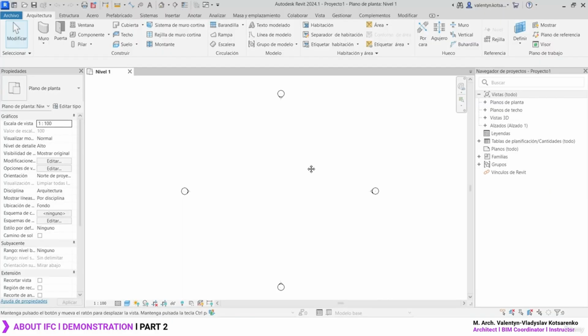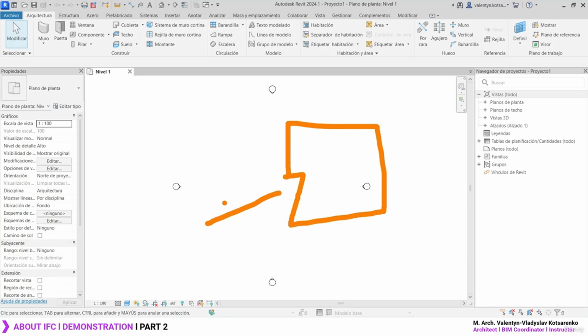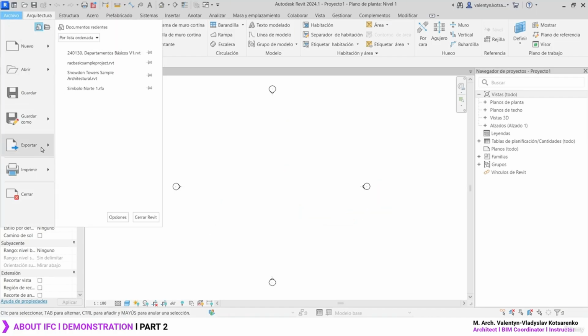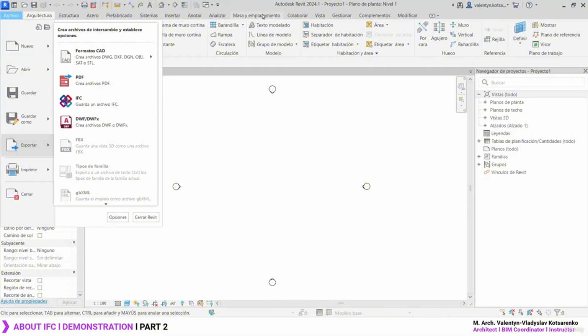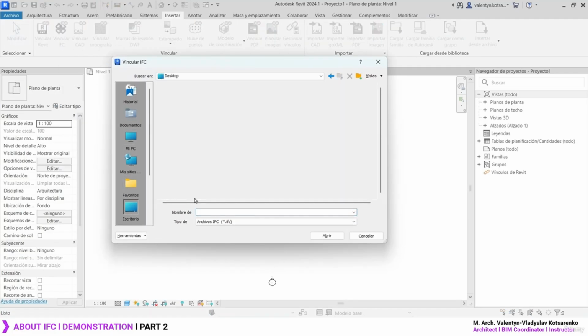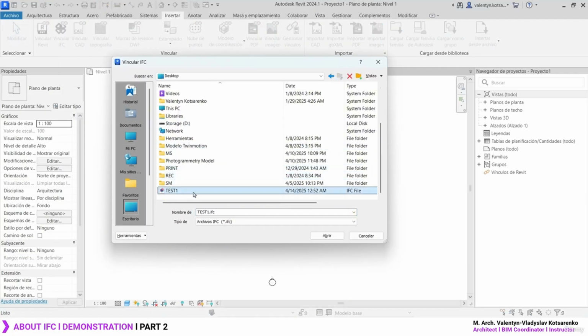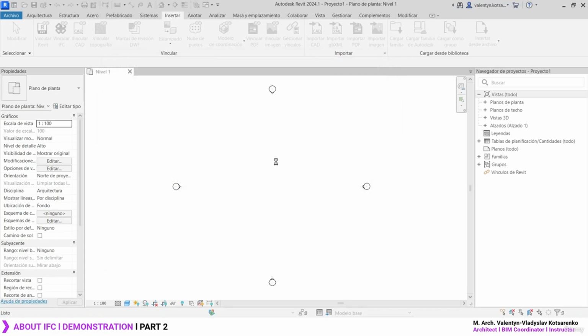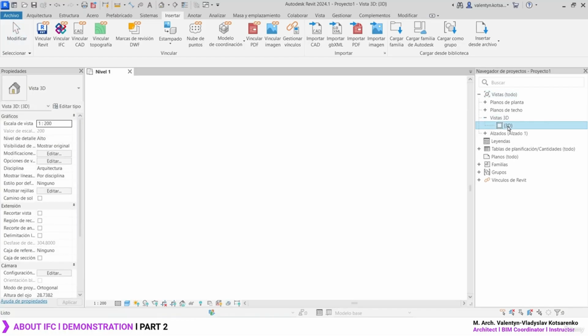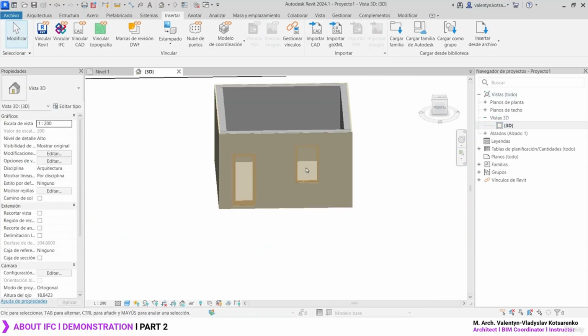Let's say I have Revit over here. So in Revit, I need to model the second volumetry based upon the first volumetry generated in ArchiCAD. What we can do in Revit is, for example, do the same process. We can go over here to Insert. We can link an IFC file, and I'll take the one I just exported from ArchiCAD. So open this up real quick. As you can see, it's not going to import the model exactly because some data loss is going to happen in Revit.